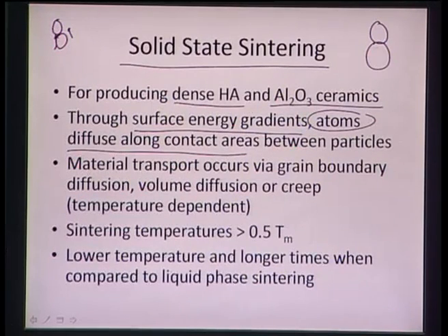So we will see first of all a necking which can occur between the two particles as the diffusion goes along at higher temperatures. In solid state sintering, we are not allowing any phase to reach a liquid regime. So the holding temperatures for solid state sintering are much lower than for liquid phase sintering. That is one of the differences between solid state sintering and liquid state sintering, and in this particular case we only see atomic diffusion happening to cause the densification.